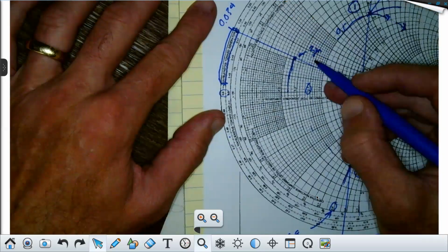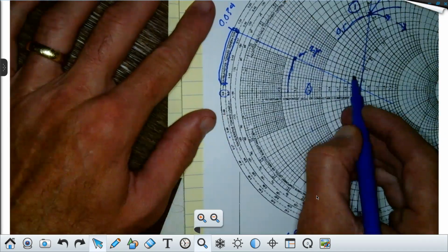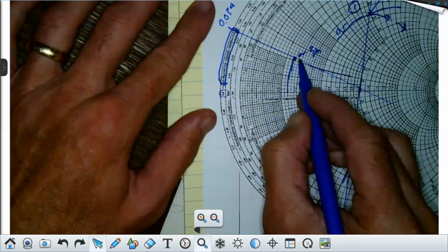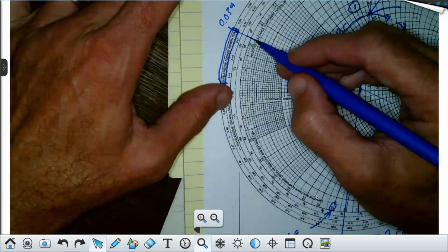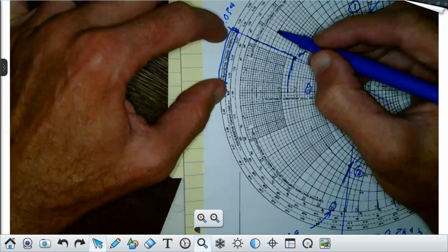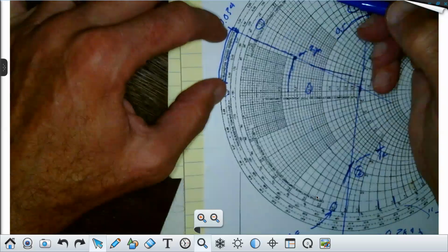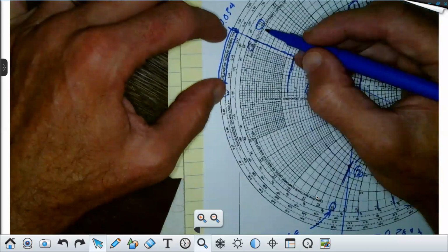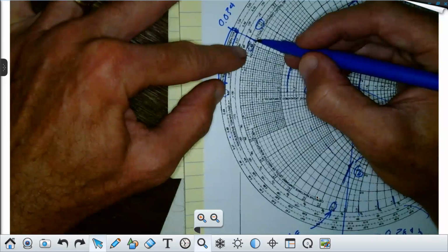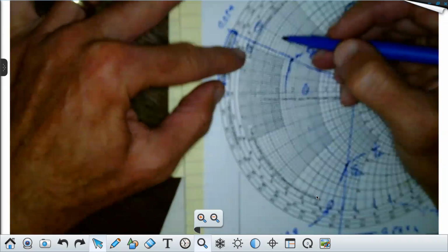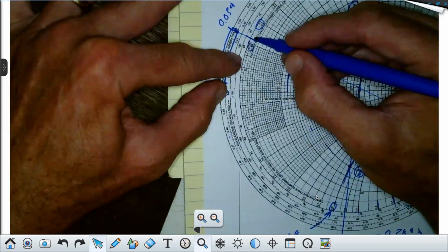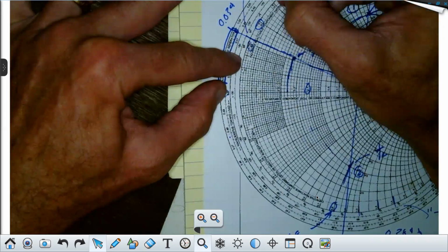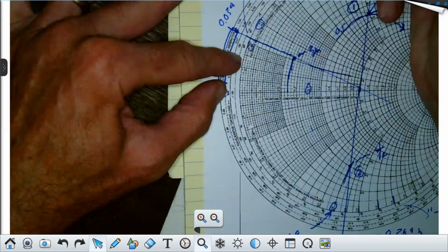What's the imaginary part? Here's where you got to take a look at this line shooting out right here. Well, actually, it's this line. What do you get? Take a look out there where this intersects right here. Can you all read these numbers? That's 0.3, right? That's 0.2, so it's 0.22, is that right? Plus J 0.22. Take a look on yours. This number is about J 0.22, isn't it? Go ahead, check on yours, guys. Could you explain one more time how you got that point?